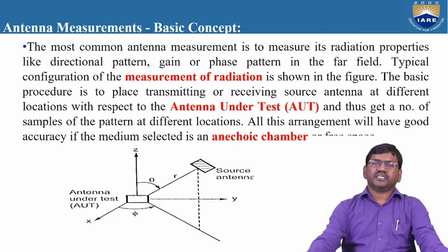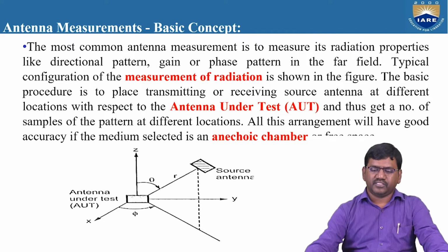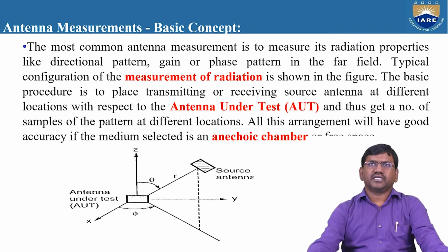Let us start with the basic concept of antenna measurement. How to measure, what is the setup required for measurement of radiation? The most common antenna measurement is to measure its radiation properties like directional pattern, gain, or phase pattern in the far field.